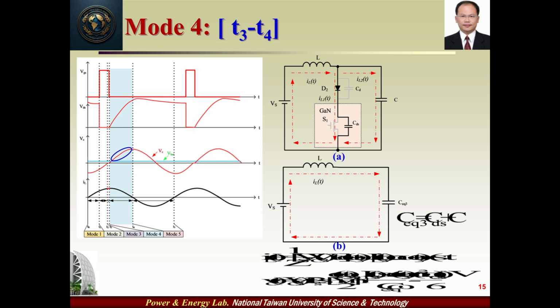In this mode, the sinusoidal loading current resonates to 0, that is to say, it stops drawing energy from the battery module at T equals T4. When T equals T4, the resonant inductor current IL,T decreases to 0, and this mode is ended.